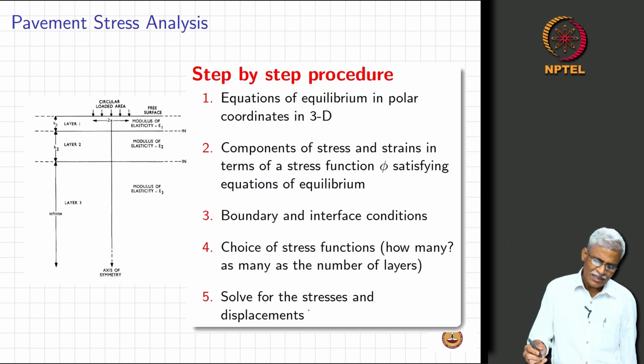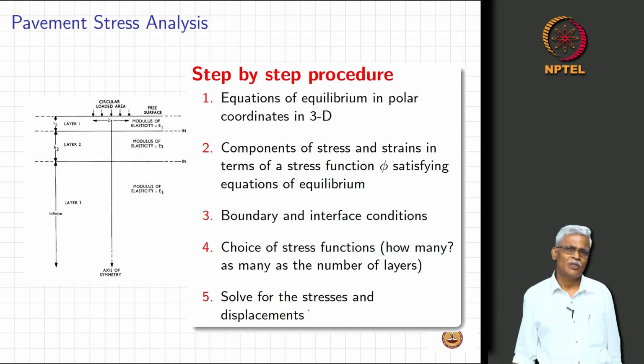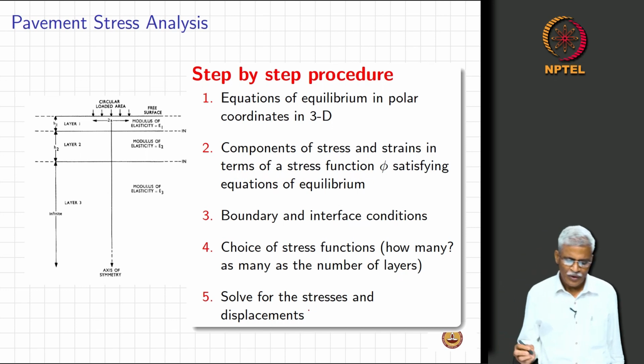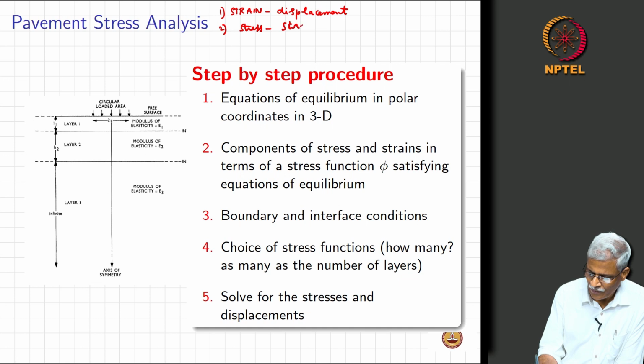So, what exactly is the step by step procedure, and in fact what exactly is any step by step procedure for solving any stress analysis problem? What is it that you will first do? You will write the strain displacement relationship, that is the first thing. Then you will write the stress strain relationship, which is your constitutive model.